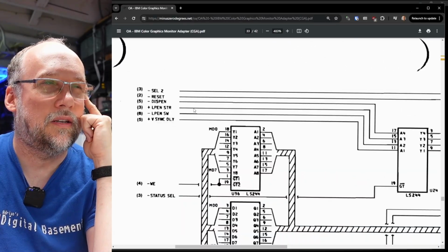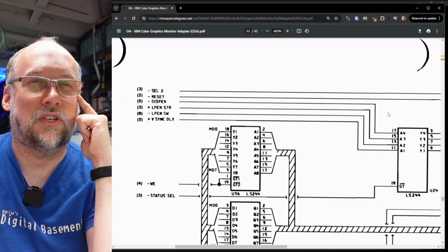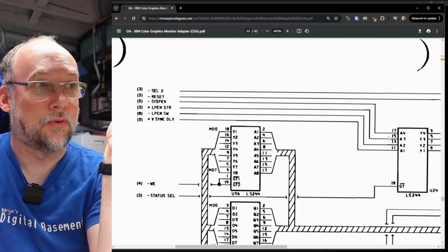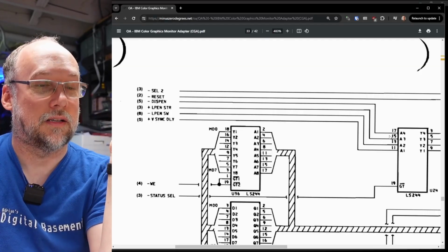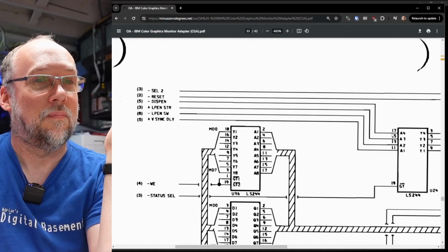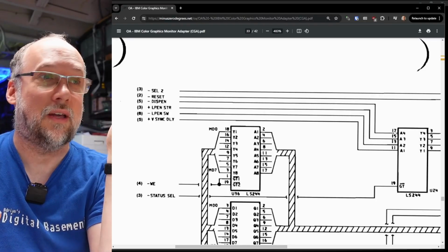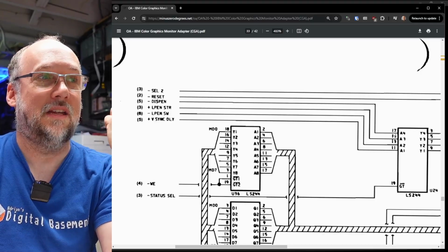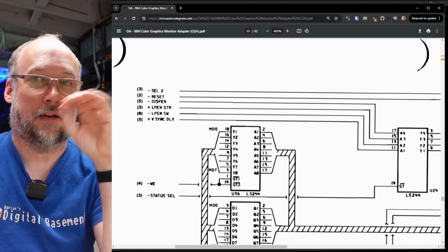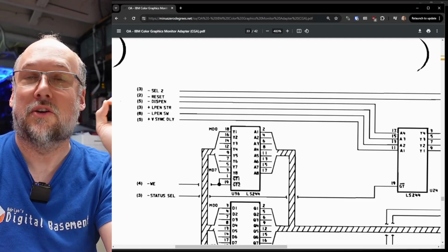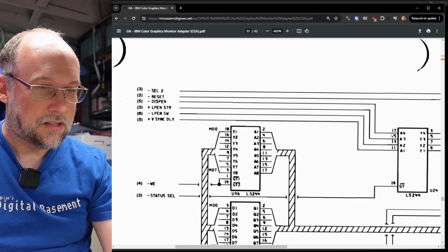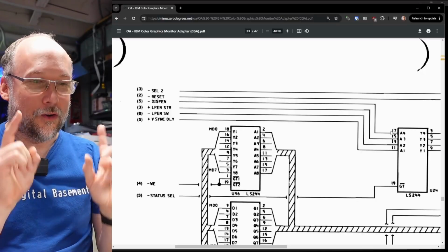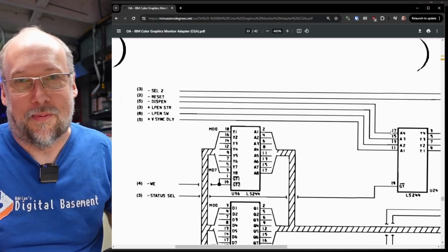So I think all we need to do is cut this connection here that goes into pin 17 on this 244 and keep this grounded all the time, and that will trick DOS and the BIOS call into thinking that the vertical or horizontal retrace is happening, and it won't wait to print characters. It will create even more snow for even printing normal characters on the screen, but it should create that speed up that we're doing in software with those utilities, but it will be all the time. So let me go try to do that mod and let's see what happens.